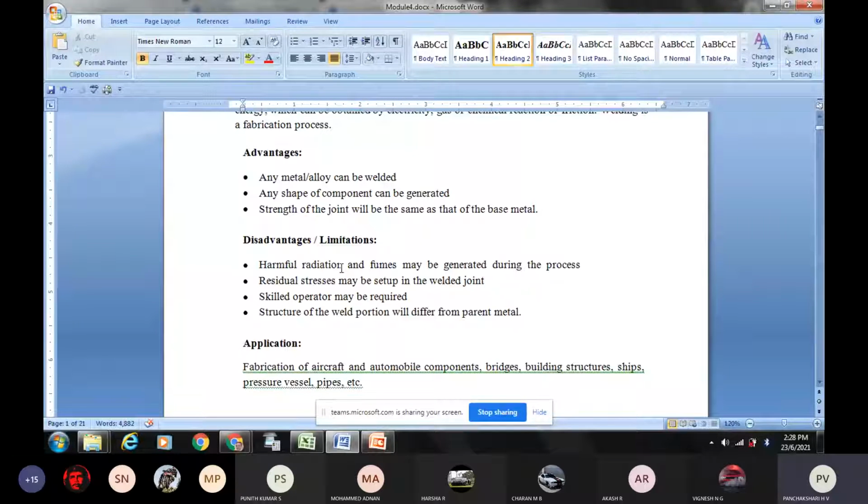That heat treatment process is called stress relieving heat treatment. This heat treatment topic you already studied in your third semester subject, material science. So what is stress relieving heat treatment? We heat the metal up to the lower critical temperature. Lower critical temperature is designated A1. In the case of steel, it is 727 degrees centigrade.